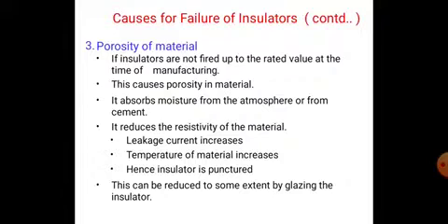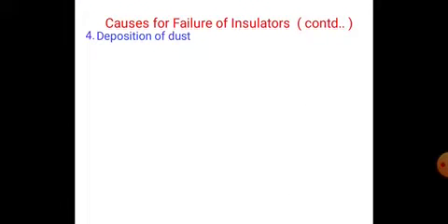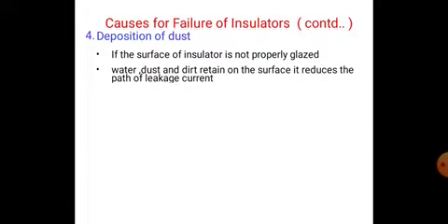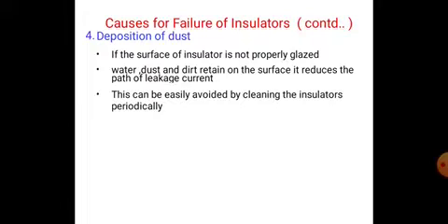Because of these atmospheric conditions, the insulators will fail. Next, the deposition of dust. If the surface of the insulator is not properly glazed, water, dust and dirt retain on the surface. It reduces the path of leakage current. This can be easily avoided by cleaning the insulators periodically.